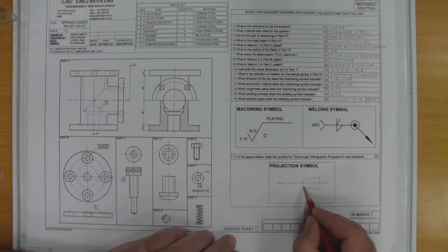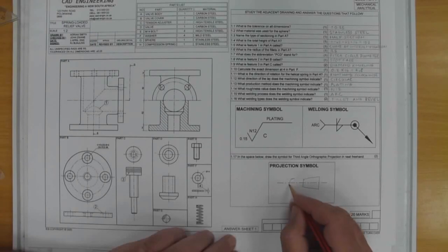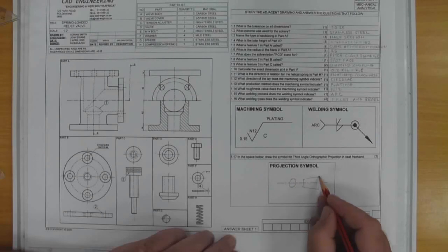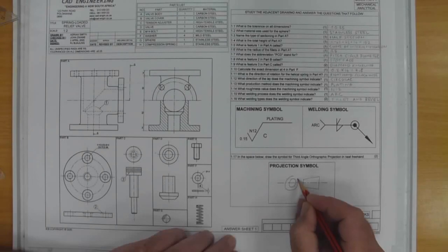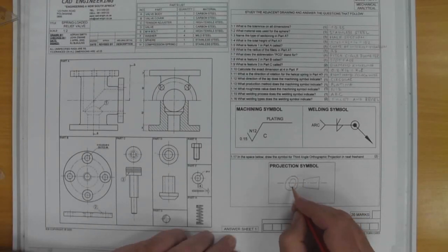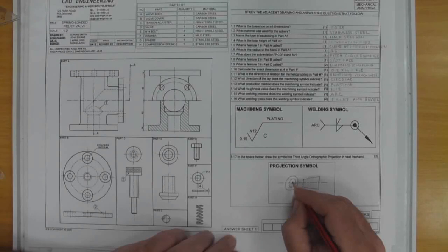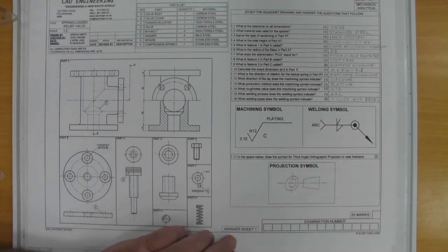Now when we draw the circle, we try to have the circle on the left hand side, because the tapered roller is always the front view. Third angle, the left view is on the left of the shape. So when I draw my circle, I try and line up my circle with this line. There is that circle, needs to be a bit bigger. Now we've got the horizontal center line, and we then need to include the vertical center line.